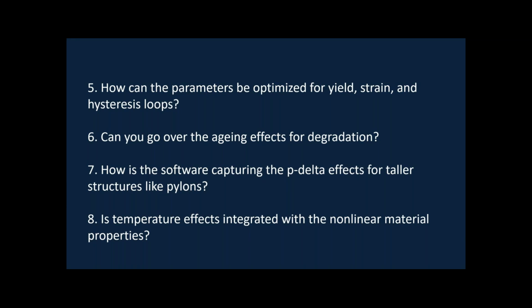The eighth question is, are temperature effects integrated with the nonlinear material properties? Currently the temperature effects are not integrated. In the case of nonlinear material properties, we only have the material nonlinear properties in which the material stress strain curves can be specified. The temperature effects are only considered in a linear analysis, wherein the temperature coefficient is utilized by the program to consider the temperature rise, fall, or the gradient type of loading.